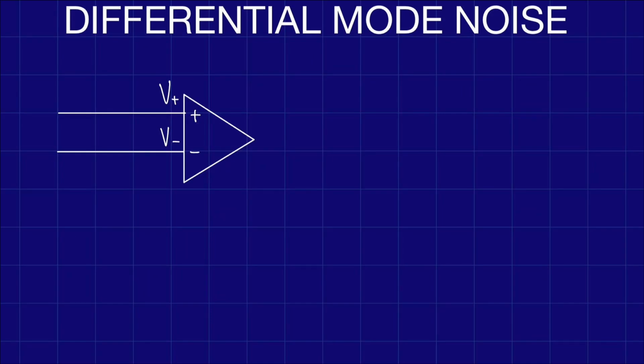So right here you can see a design of an OpAmp, and how they are made is that at the input they have a very big resistance that we can say is also infinite input resistance, so no current can enter here. So what we actually amplify here is not the current but the voltage, specifically the difference between those two inputs. So for example, if we have 2 volts up and 1 volt down, we will amplify the difference between them, which is 2 minus 1 volts.